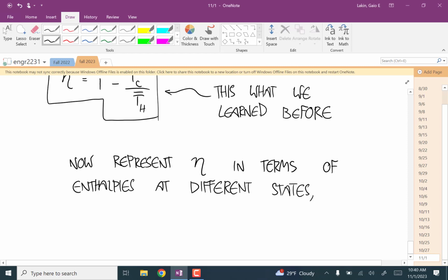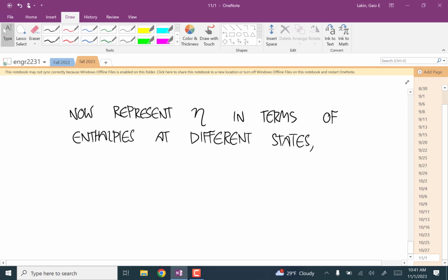And then I'm going to give some examples. Since enthalpies are properties you can look up in a table, what we're going to see for problems is you have this cycle and you know the pressure and temperature here, the temperature here, the pressure here. How can you go around using what we know about this ideal Rankine cycle and figure out what the efficiency of this thing is?